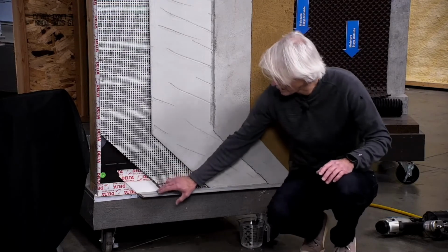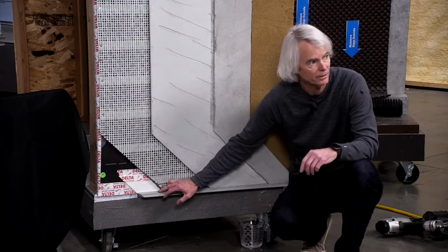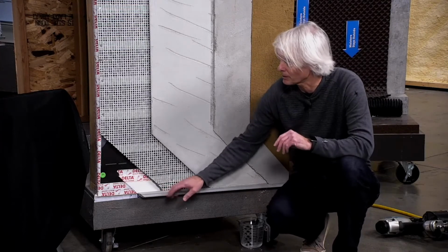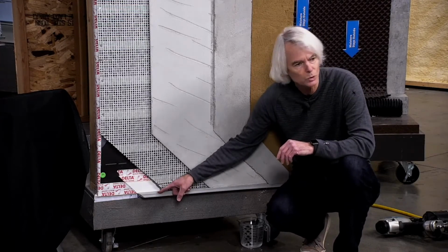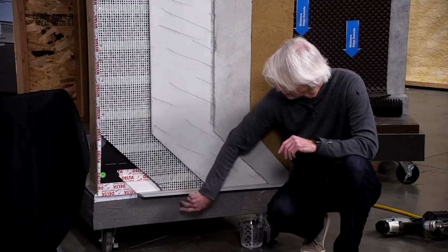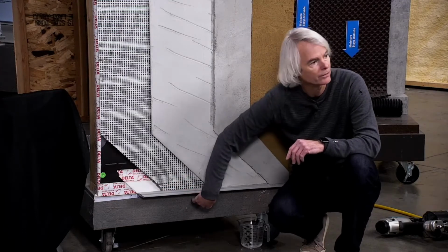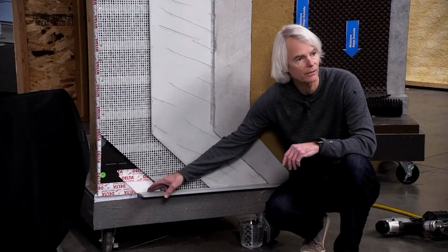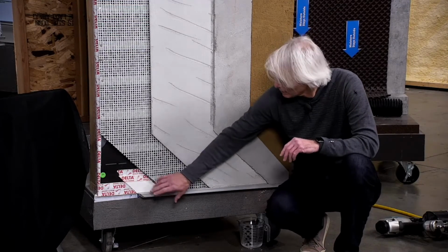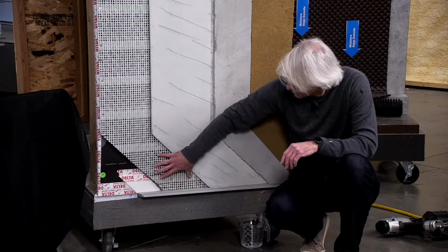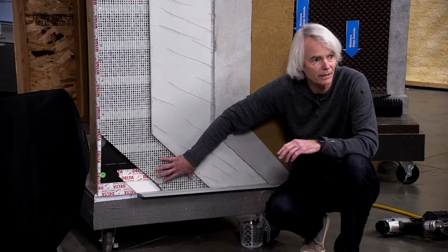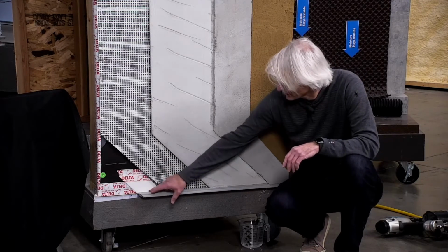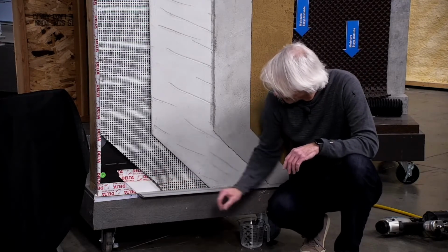Now, we like to try different products here at the CI Live facility, so we got our hands on a different product. It's not a metal product, but here it's an extruded PVC product that has a flashing channel built into the bottom area here that you can't see, and then it actually has an integrated weep screed component here on the top side that the rain screen product actually lines right up into and facilitates that drainage of what might become on the back side of this wall.